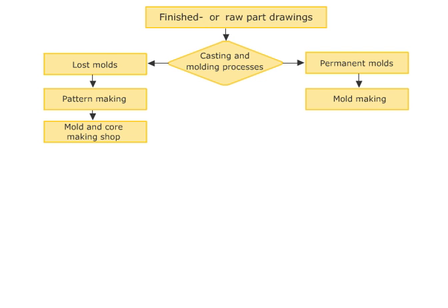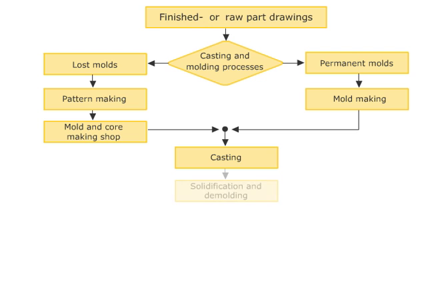The next process step in casting-related production is the casting step itself, hence filling of the mold with liquid melt. The most frequently used casting process is gravity casting. Here, sand or permanent molds open on top are filled with melt utilizing gravity. After the casting process, the casting must solidify and then be demolded. The time for solidification can vary quite a bit.